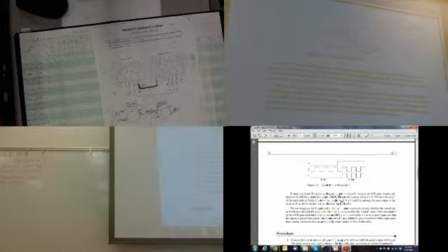Now, what you're going to have to do is notice the piece down here, the magnitude says 1 volt per division. Well, we're looking at a 5 volt signal, so you're going to have to turn the knob under the blue signal to the left until it says 5 volts per division. And you have to do the same with the yellow. You can see that those were hidden because that was right on top of that.